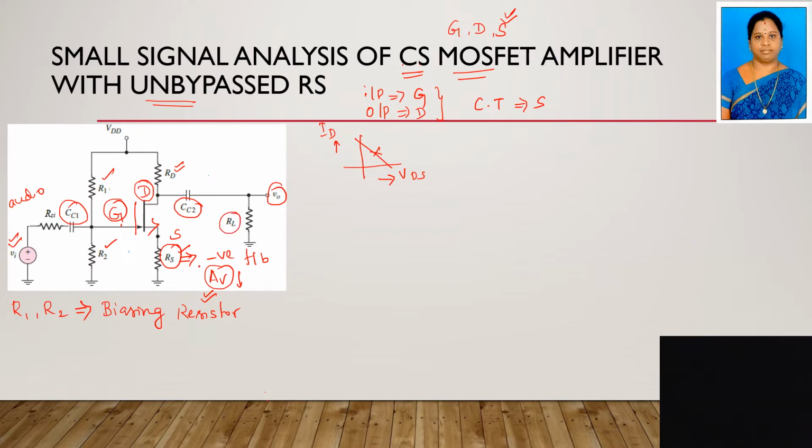See here, from here to here, it is the amplifier. From this point is the load, and this point is the input signal, that is audio or video signal. So the output of the amplifier is given to the load. It may be a speaker, right? This may be your speaker. So this output is given to the speaker. That speaker has some internal resistance that is represented by RL here.